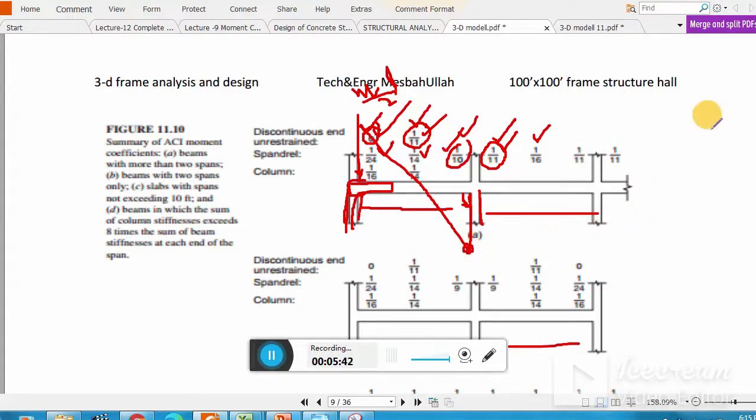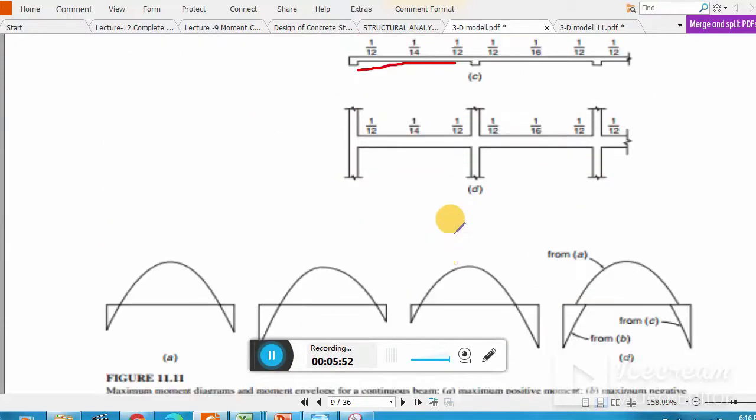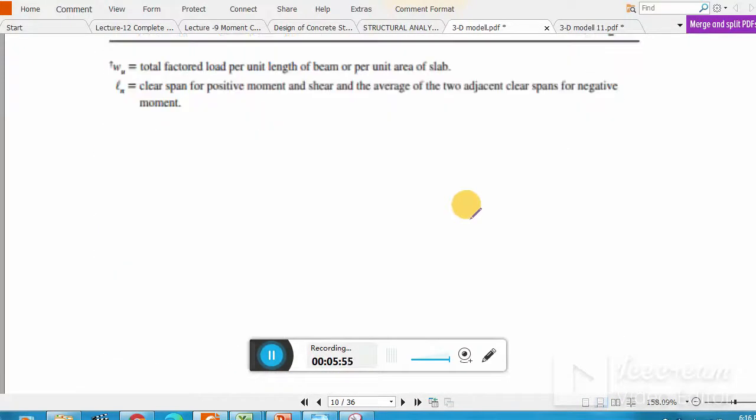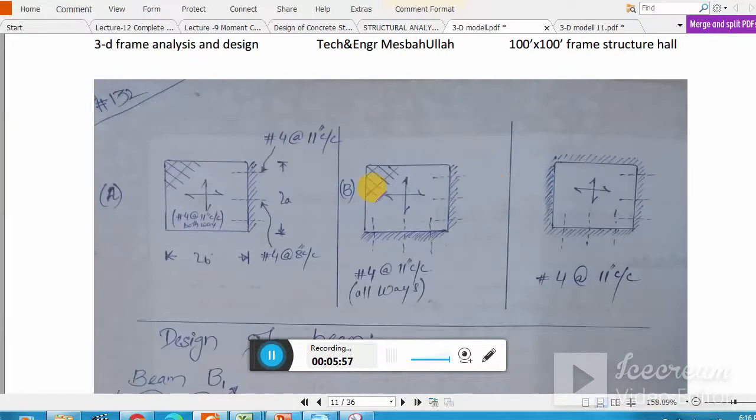Similarly for the exterior, this is my exterior panel, or this is my end panel, and this is my interior panel. Okay, so I will explain. Here we have the final detailing diagram, remember, that we basically discussed in lecture number 6. And you see this is the extra bar which is provided in panel A at the support, at the column, at the beam, sorry, beam.